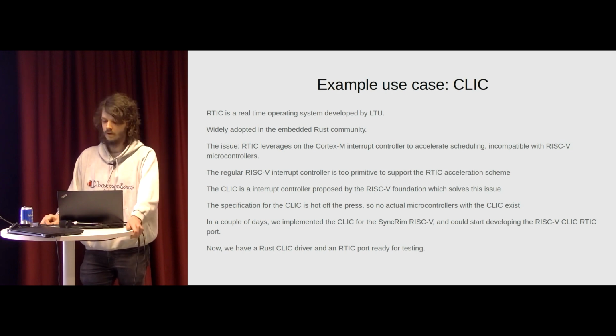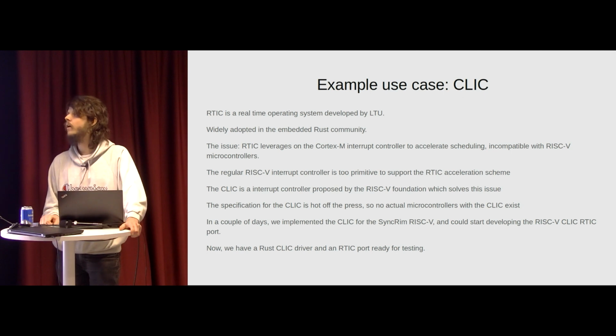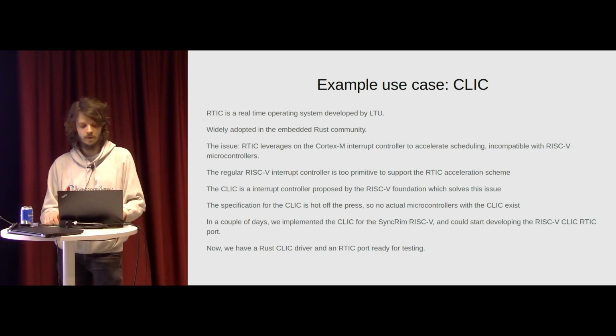And so implementing this component took like a couple of days, and now we have a Rust CLIC driver and an RTIC port ready for testing for when reality catches up. And actually last evening I found this really obscure Chinese manufacturer that is claiming they're packaging their chips with a CLIC, so maybe I'll order that and we will see where that goes. The same company has made a fork of QEMU, which implements this obscure chip, which I was trying to get to work yesterday, but I didn't quite finish it.